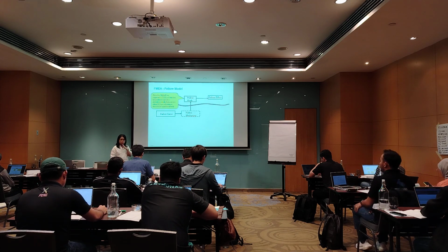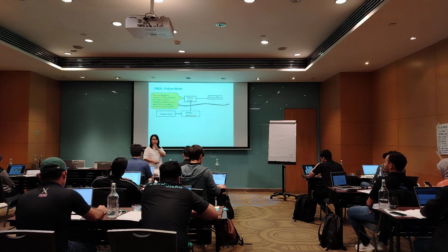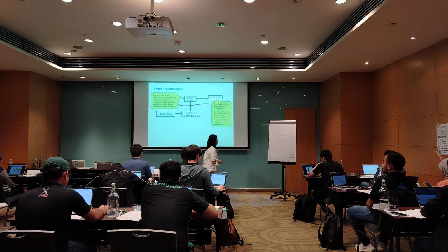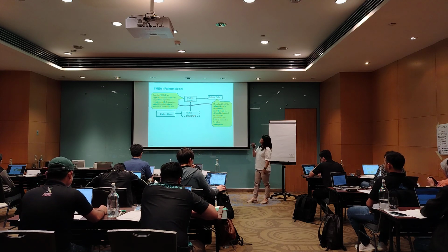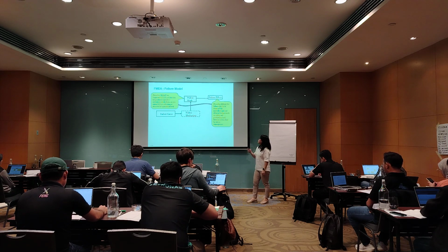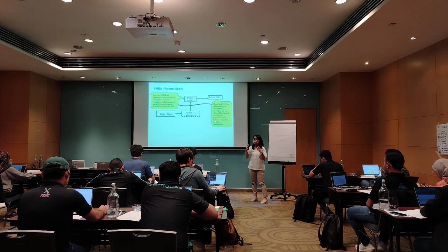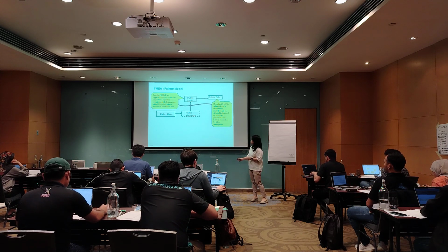Failure mode is the what that you see. What you hear, see, smell. And then effect is, what are the consequences? What happens if the failure happens? Immediate effect. Okay, and then the severity is how high the impact level is. Then you define it in the consequences.